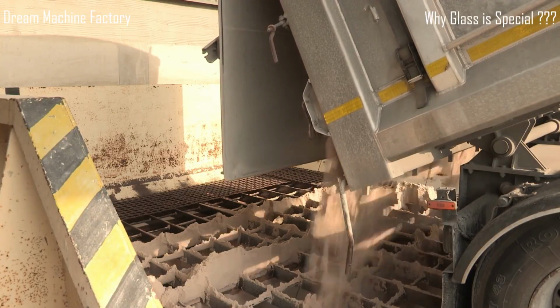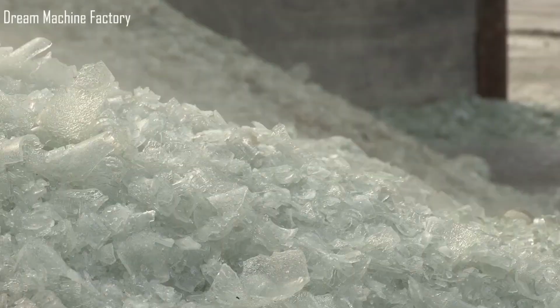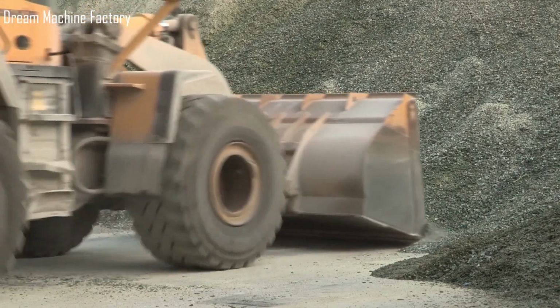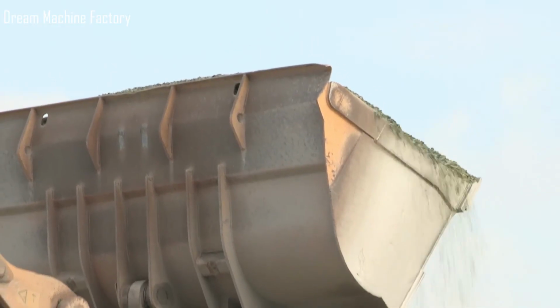In Stage 1, high-purity silica sand, soda ash, limestone, and recycled cullet are precisely weighed and blended into a homogeneous batch. Optional metal oxides or colorants may be added at this point to achieve specific glass colors or functional properties.